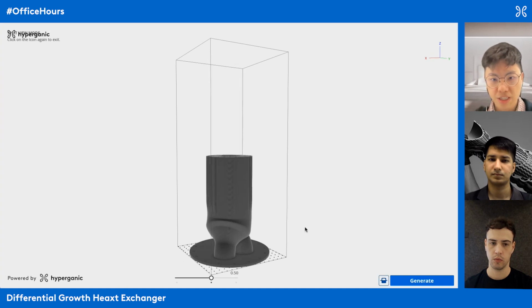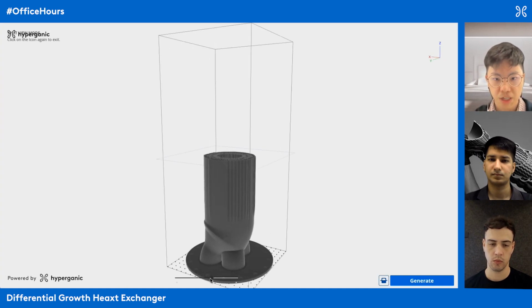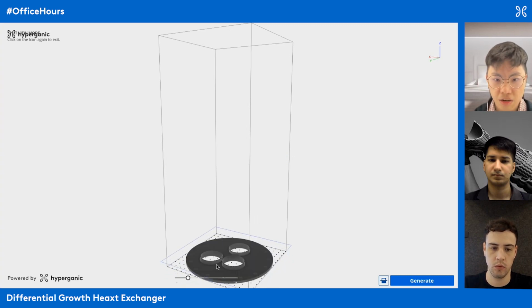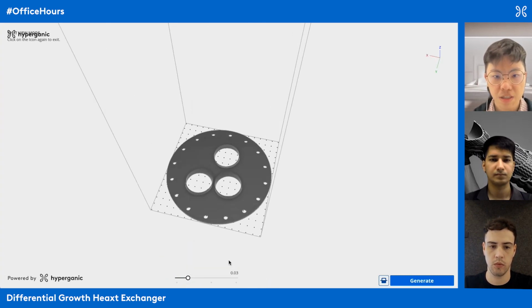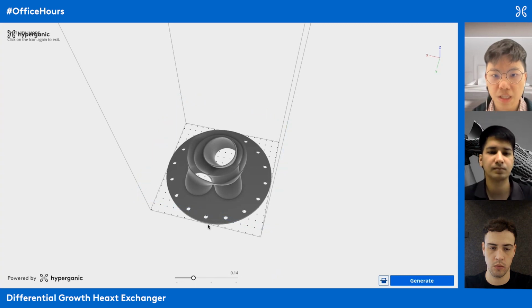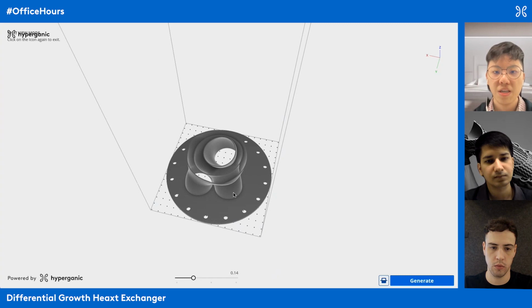So to illustrate this, I just want to show the cross-sectional region at the transition areas. So you can see that I start off with 3 channels, and as they go in, they start to converge into each other. So you can see that for these 2 channels, let's call this channel 1 and channel 2, if I don't increase the radius, the fluid is going to end up being blocked, right?